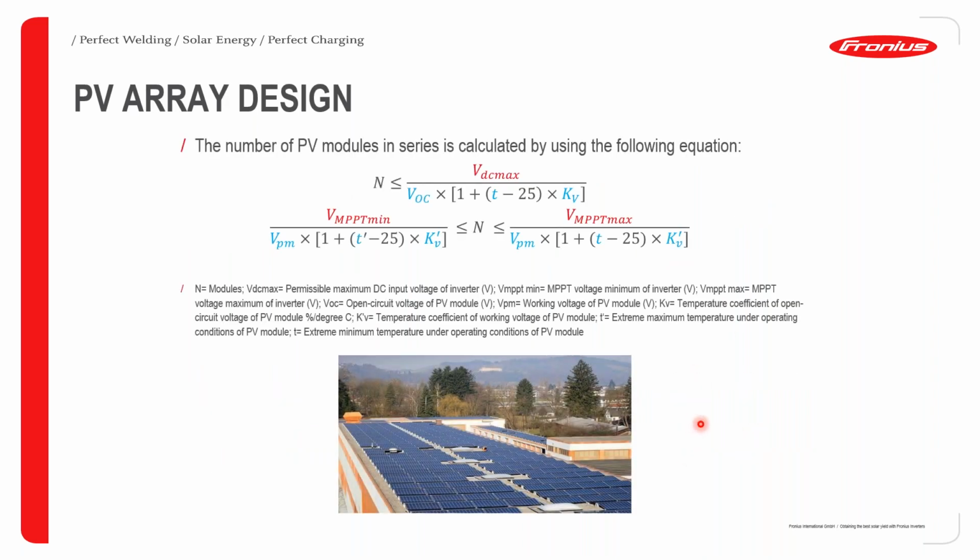Good. So, still talking about PV array design, it's also important to ensure that the number of modules per string that is used meets the optimal value, meaning that it is important to calculate the number of modules that's going to be used in the system so that we don't oversize it beyond its design specification.